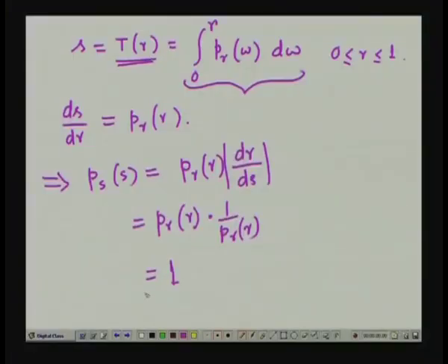And we have seen earlier that a high contrast image has a probability distribution function, or a histogram, which has pixels having intensity values over the entire range 0 to 255 of the pixel values. So, if I go for this kind of transformation, as we are getting a uniform probability density function of the processed image, then this is what is going to enhance the contrast of the image.